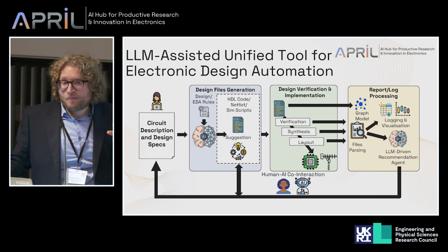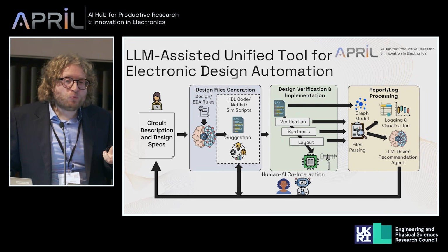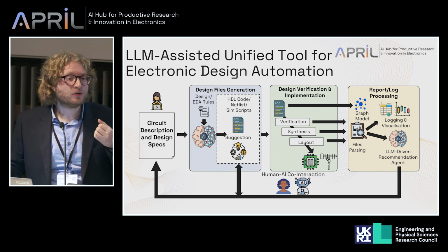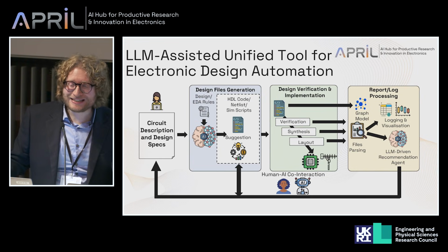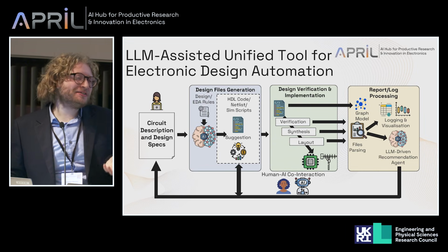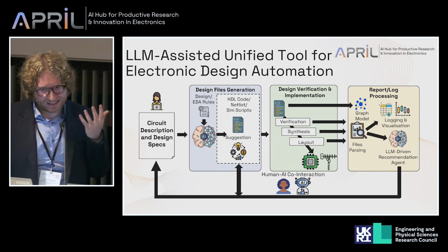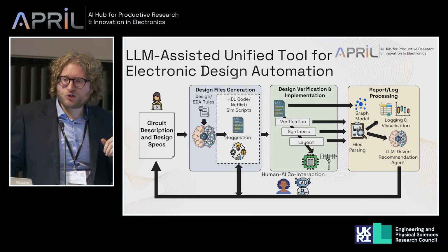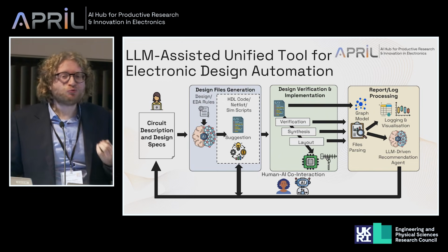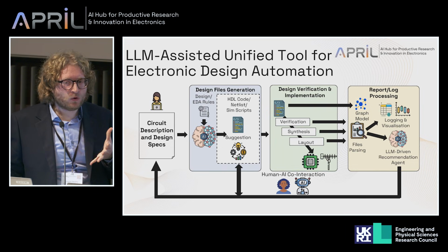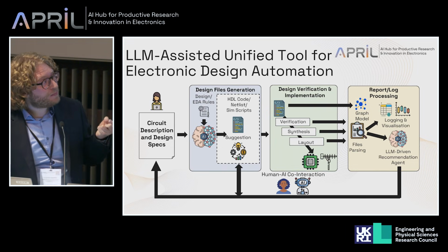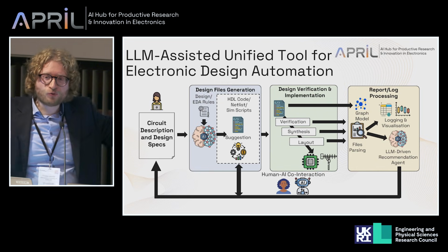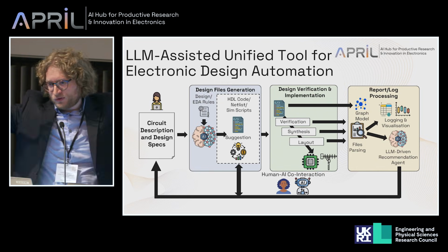From each design step, as we know in the commercial tool, we may get both report files about resource occupation, power dissipation, and delays, but also log files. And we know how verbose these files are. So in order to feed all this information to artificial intelligence, to large language models, to identify if something is going odd, we decided to implement also a Python-assisted report parsing that takes all this information and compresses them in a sort of dictionary.